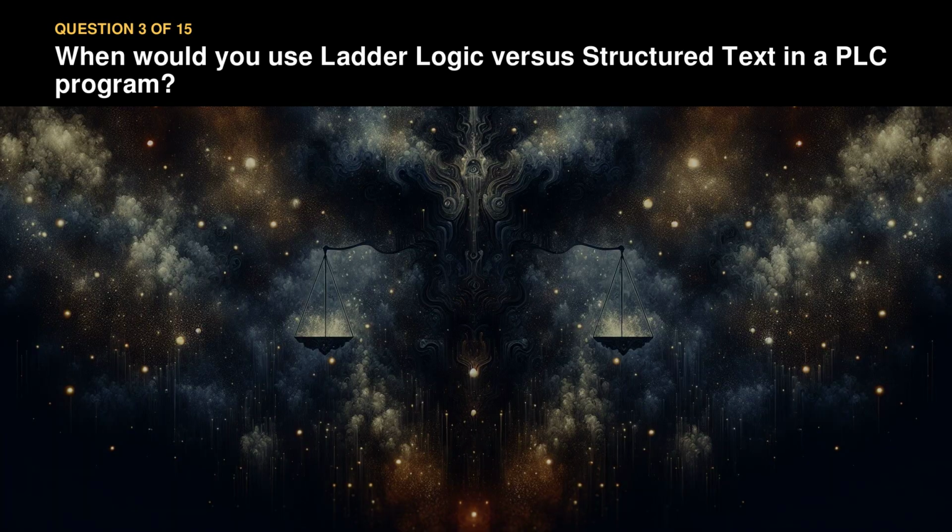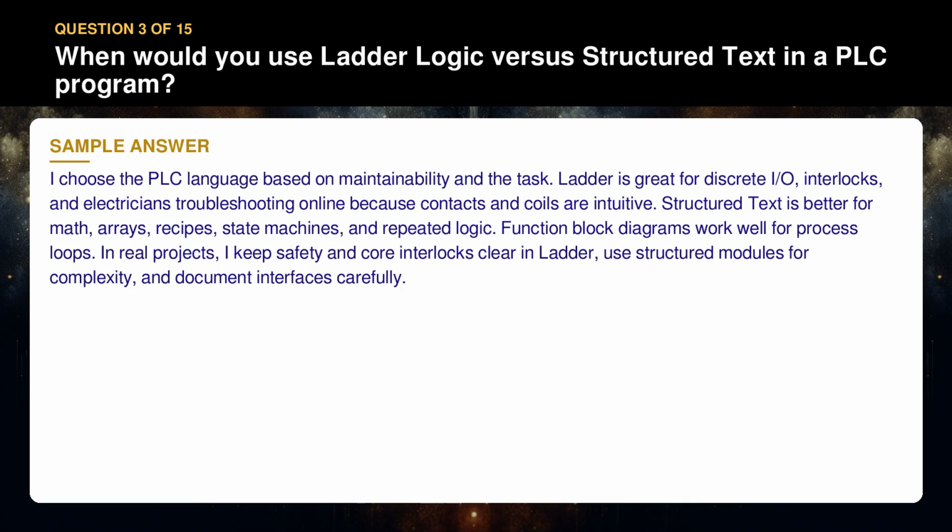Question 3. When would you use ladder logic versus structured text in a PLC program? I choose the PLC language based on maintainability and the task. Ladder is great for discrete I/O, interlocks, and electricians troubleshooting online because contacts and coils are intuitive. Structured text is better for math, arrays, recipes, state machines, and repeated logic. Function block diagrams work well for process loops.